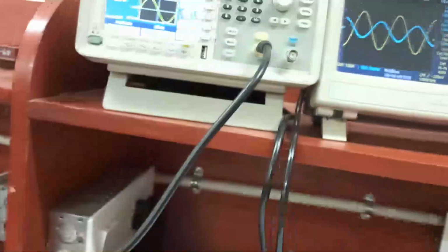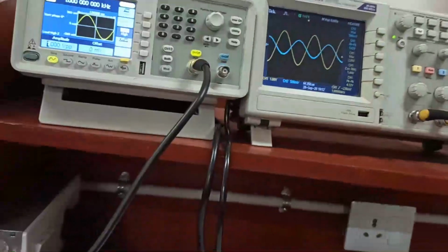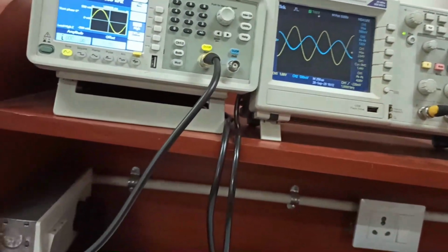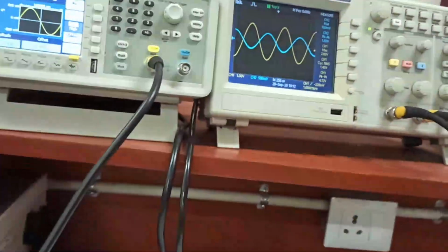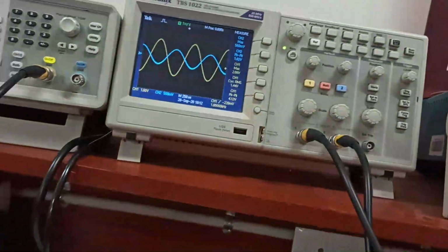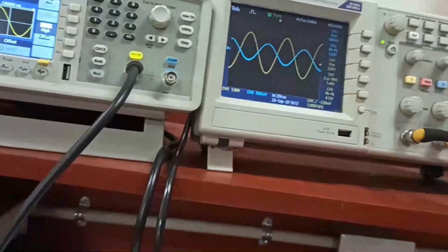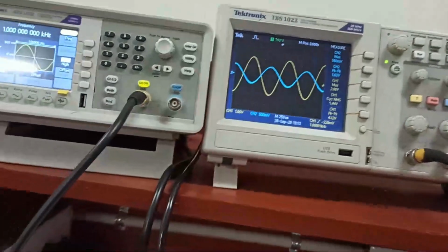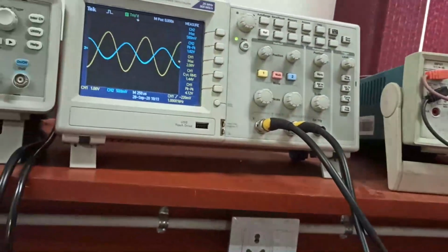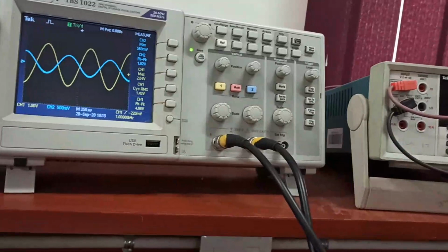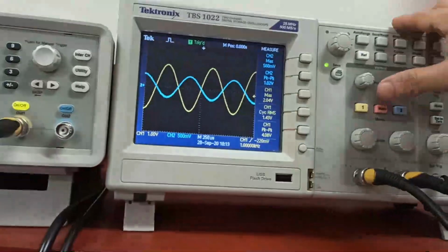Now another thing is there, called input output characteristics or transfer characteristics. See, in the oscilloscope there is another mode, which is called XY mode. What we are seeing now is YT mode. YT mode means in the y-axis I am seeing the amplitude, and in the x-axis I am seeing the time. I can change this to XY mode also. XY mode means in the x-axis I will give one signal, and in the y-axis the other signal. So it will plot the transfer characteristics, the input output characteristics. That I will show you now.